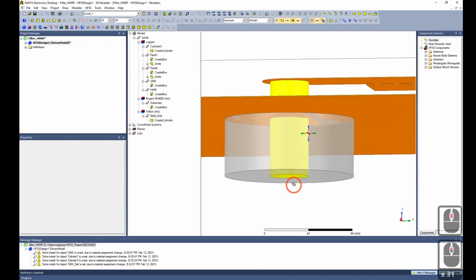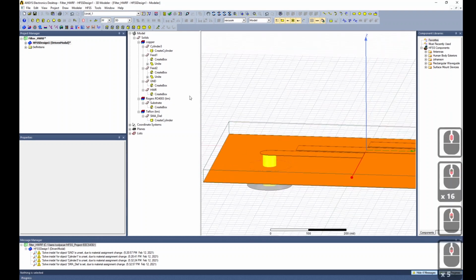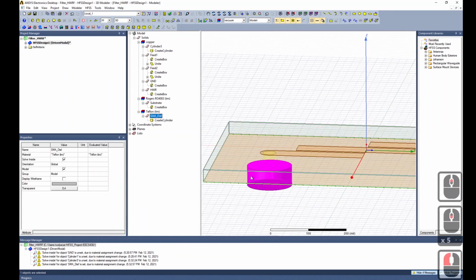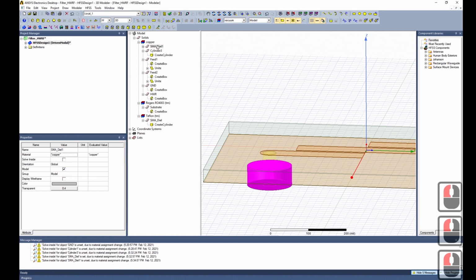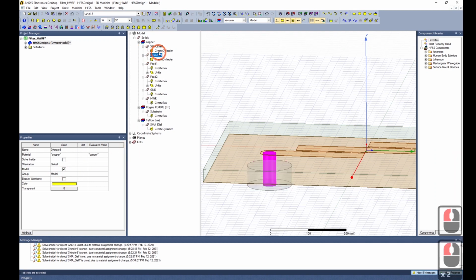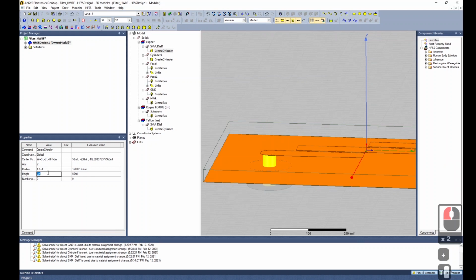We also need to add an outer conductor for the SMA connector. So let's see, once more, I'm going to build it out of the SMA dielectric. So let's copy that guy. This is going to be made of copper. We're going to add an additional thickness T to the current radius. Oh my goodness.